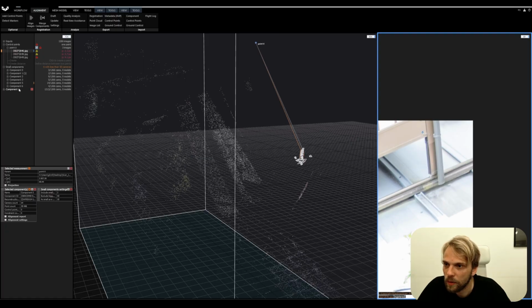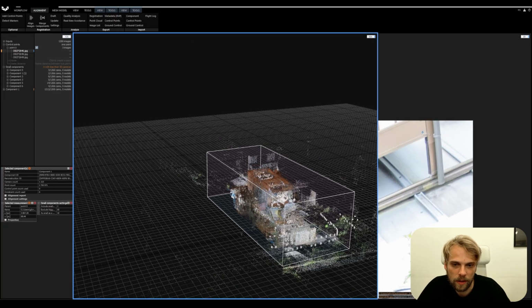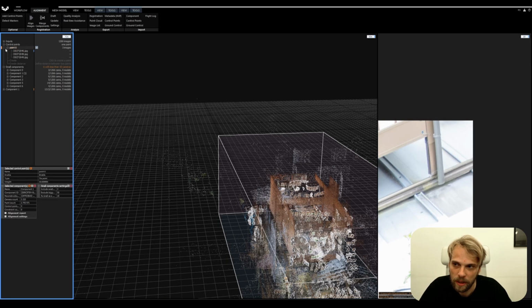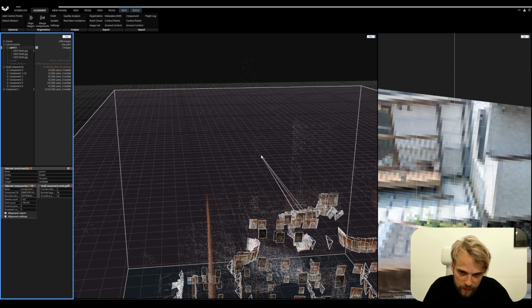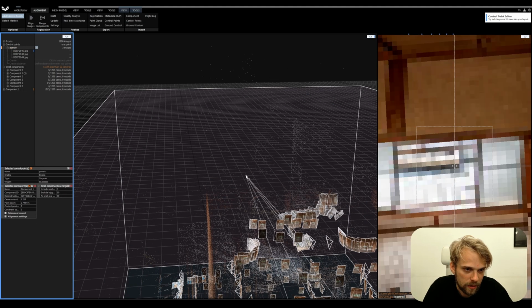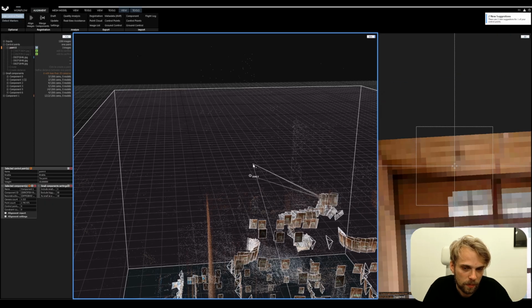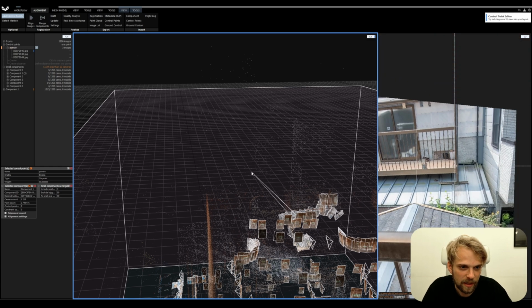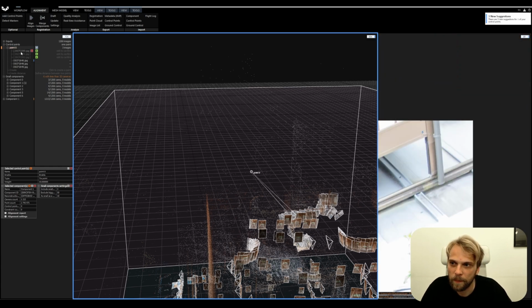That's fine. And now in my big component, component one, I want to also kind of anchor to that particular bolt. So I choose point zero here. I press F3 and I try to get as close as possible. Oops, that was not good. Control Z, F3 again. I will try to get as close as possible to that bolt.